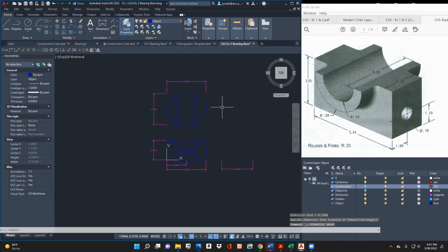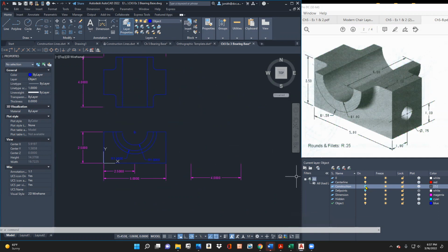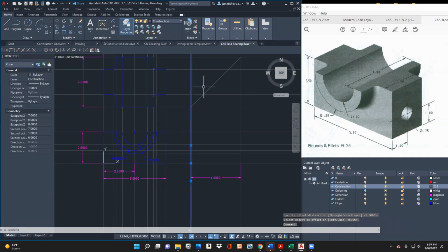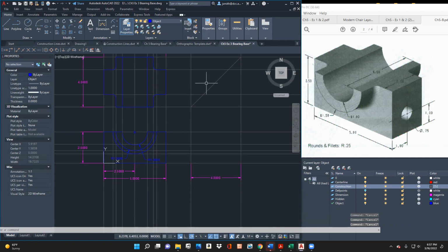All right, so let's build the front view. So that's the front, top, and the right view. Let's turn the construction line on here. The nice thing about this is I could measure it. It's probably the better way to do it, but I could also offset. I recommend that you think about it and not do this, which would be select the object and, for example, offset.